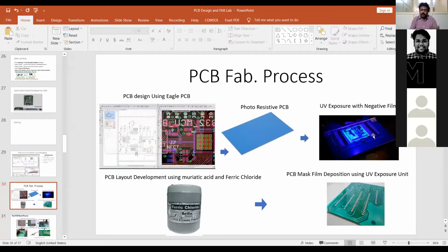When you go for a dual layer process, there are two things. One is you have to do the same process on the top as well as on the bottom. In some cases in dual layer PCBs you need to put vias, because of the USB holder or the data connectors. These things need to be connected and soldered on the bottom surface, so you need to go for wave soldering. That is the best option to solder components on the bottom surface.